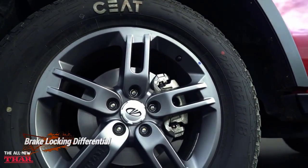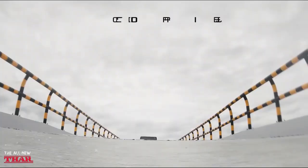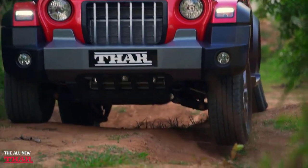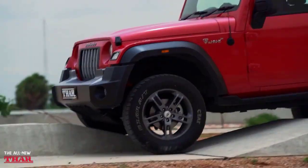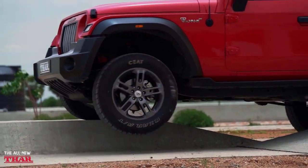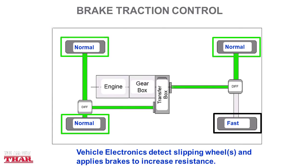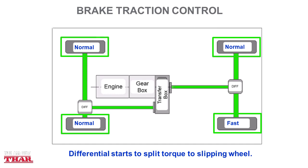Another feature in the Thar is the brake locking differential, or the BLD, or simply brake traction control. Using wheel sensors and clever electronics, if one or more wheels spin at a different rate than the others, thus receiving more or all of the torque, the computer will apply brakes to the spinning wheels. This increases the resistance on the wheel and hence the differential will start to spread the torque to the opposing wheel.